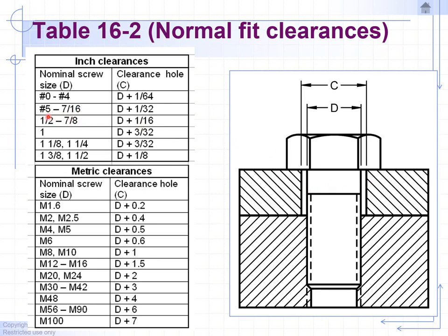Okay, and if it's below 1/2 inch diameter, then you add 1/32. So 1/32 is about 0.03. It's actually 0.03125, but it's 0.03. So add 0.03 to whatever diameter size you use. Typically, the range you're going to be working with is this range. You hardly ever go over an inch. It's very rare where you go over a bolt the size of 1 inch.